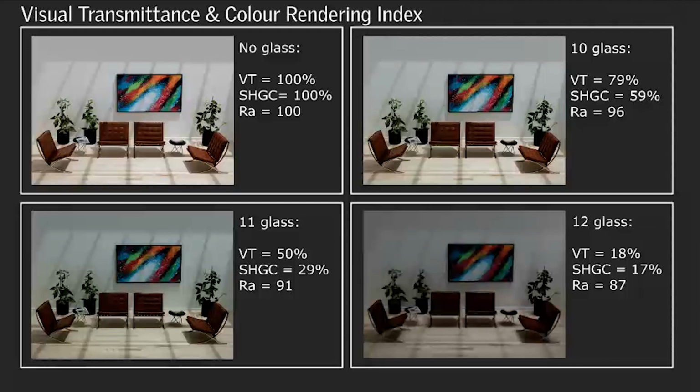Now I'm showing interior photos, but this is the same when you look out of a building. When you're inside a building looking out, your view is also going to be more gray. The colors that you see will be less vibrant when you're looking through a tinted glass. So that's one of the negative impacts of being focused on energy. The big takeaway for me is that if you're able to reduce the glazing, and energy is doing this anyway, perhaps you can go with a clearer glazing in order to get a better quality of light and color coming through and improve your view. It does put more onus on the designer to curate that view, place the windows where the view is going to be framing something nicely, but really that's good design anyways.